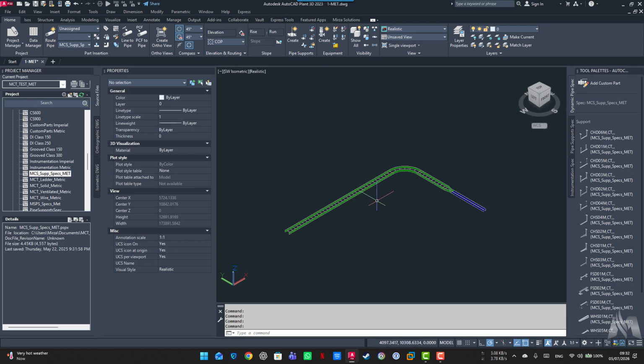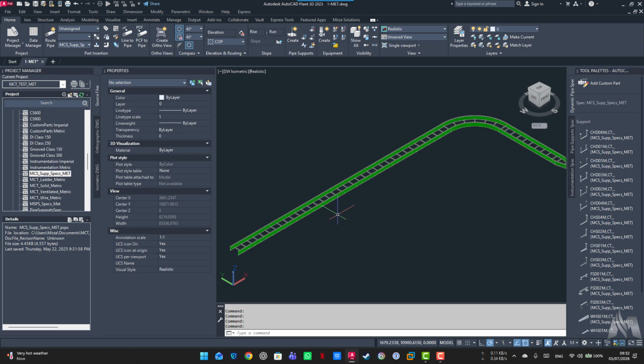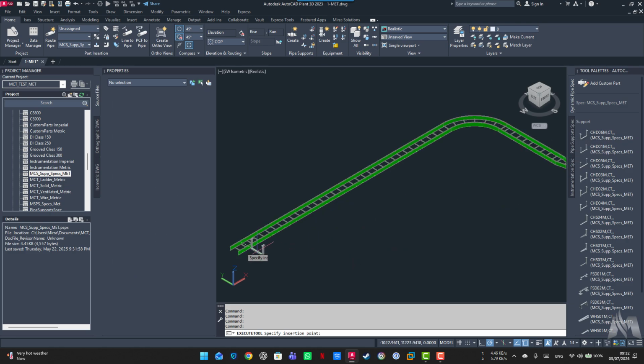Okay. After selecting the cable tray specification, you simply need to select any appropriate cable tray support. For example, I'm choosing this one, and you can see the two pointers, the two text inputs. These are basically AutoCAD asking you the distance value of placing the cable tray support on your desired cable tray section.